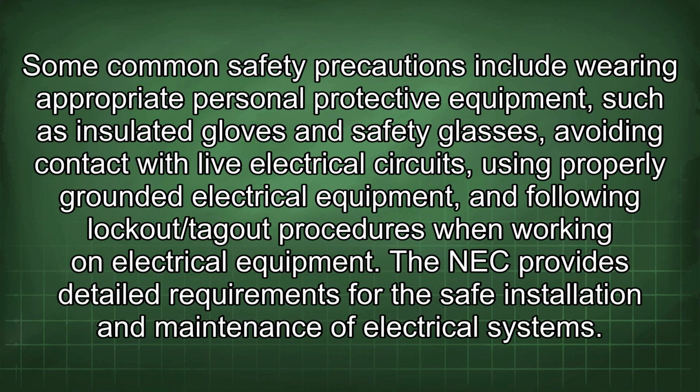Some common safety precautions include wearing appropriate personal protective equipment, such as insulated gloves and safety glasses, avoiding contact with live electrical circuits, using properly grounded electrical equipment, and following lockout/tagout procedures when working on electrical equipment.